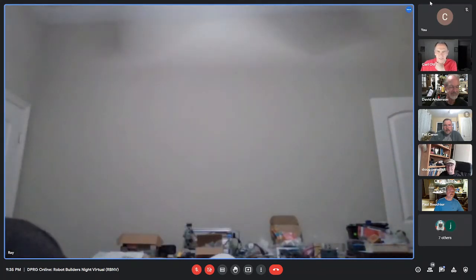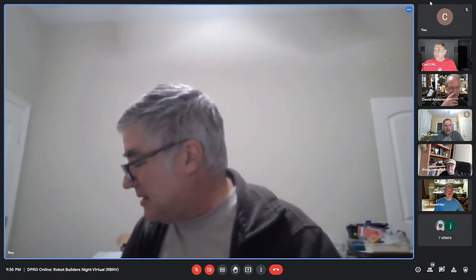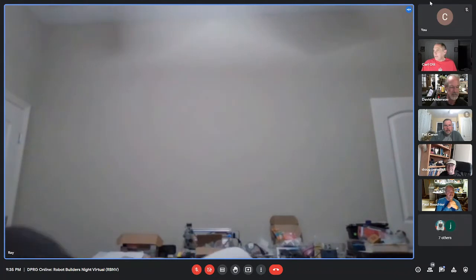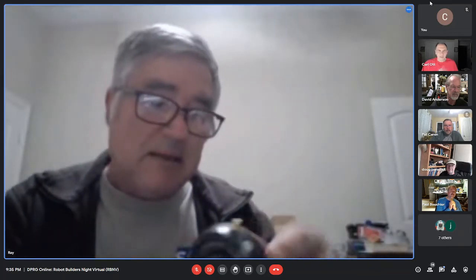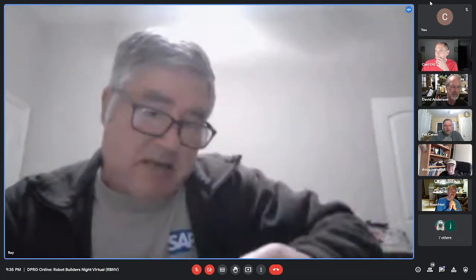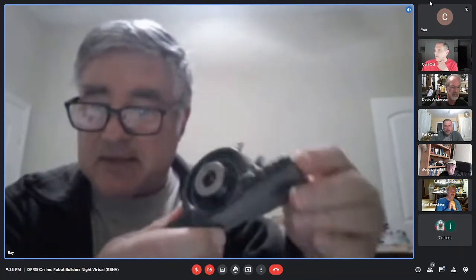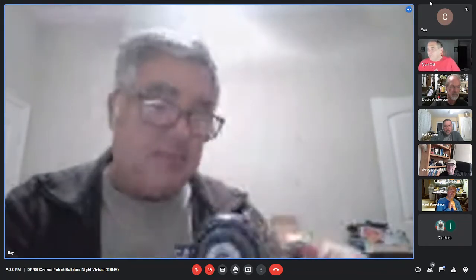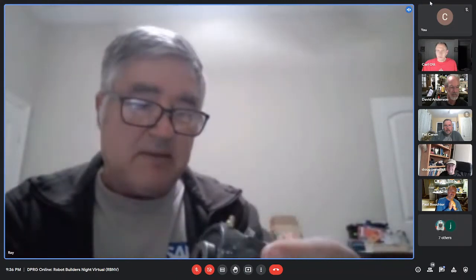So that's much lighter. Yeah. Those look like nice bearings, though. They've got little oil nipples on them and everything. Oh yeah, grease zerks. What's kind of neat about these is that they'll tolerate misalignment. So this could be off in any direction, and the bearing actually spins. I don't think I can do it by hand, but it will swivel around inside this housing to accommodate misalignment in all directions pretty much, and still support it. So yeah, they're kind of neat. It's just a pillow block is what they're called.